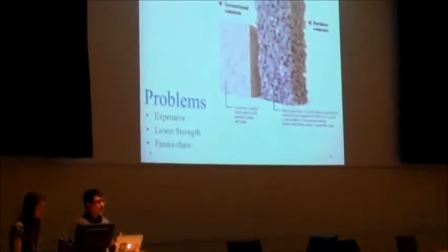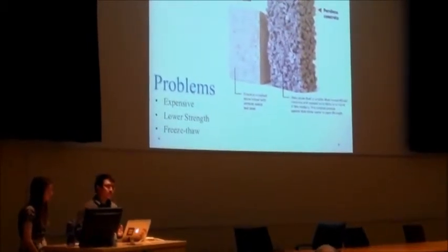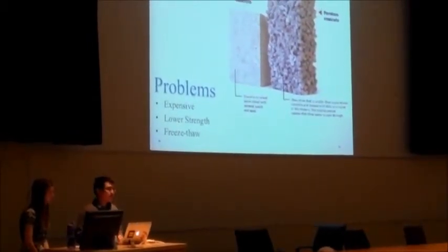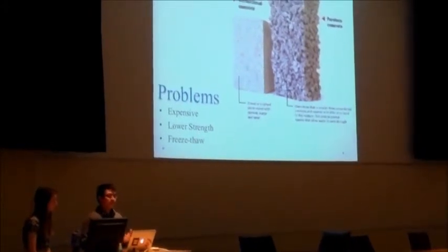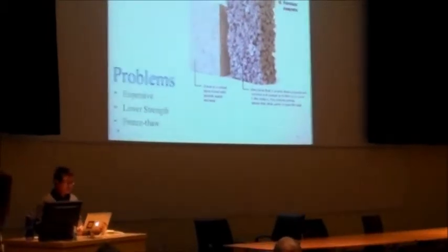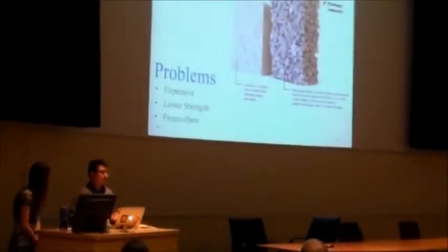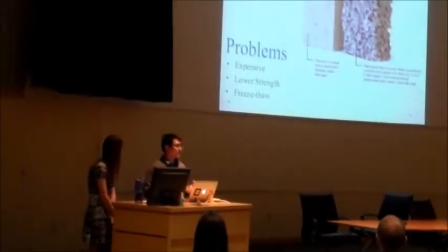And let's say you're draining water, but something happens with the pavement and it gets clogged and water gets stuck within this pavement. Now water is the only substance on Earth that we know expands when it freezes. And so if water expands within this pavement, then it can force the particles apart and cause it to break and fail.